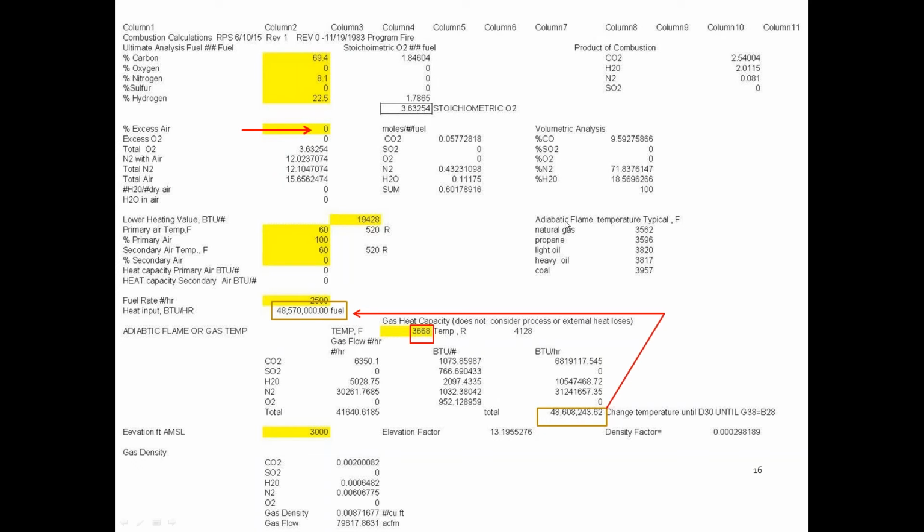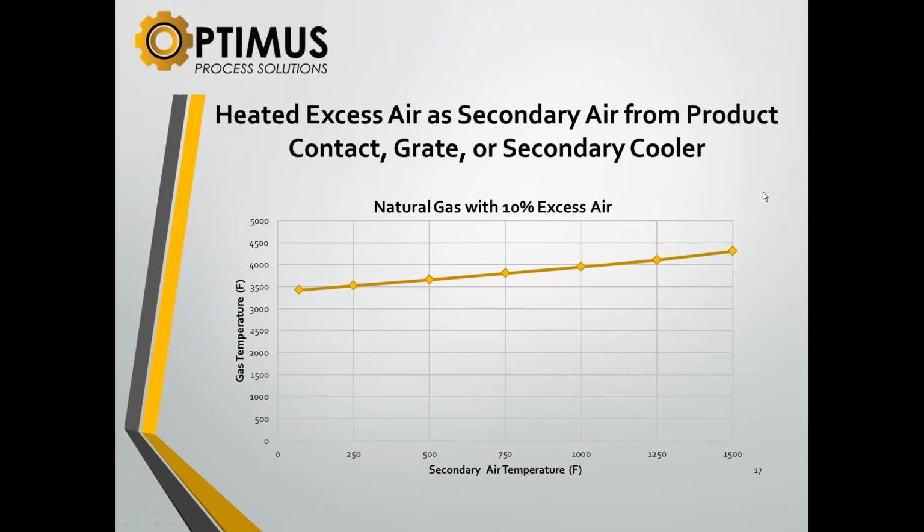So this is when you talk about the secondary air being heated? Whatever you do, if you can find a source to heat that combustion air before it goes into the kiln, that's generally a contact cooler on a lime kiln, a satellite cooler on a pebble lime kiln, a satellite cooler on a paper mill mud kiln, or a rotary cooler on some other processes. Whatever you have, you want to heat that secondary air up.